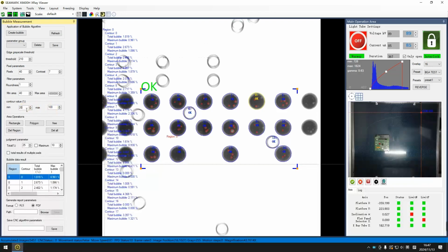And the control value, which is the edge value, recognizes a filter. So if you see this one is the through hole on the PCB board, which is not the ball we want to check. The size is smaller than the BGA ball, so we can raise the minimum value to filter this area. We can change it to 40. If it's not gone, we can fine tune the position until the through hole pad is removed. For now, it's okay. You see, we're only keeping the BGA ball pads.